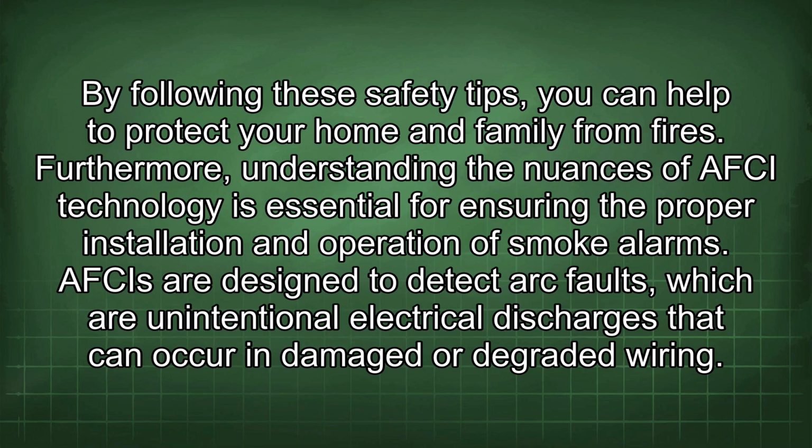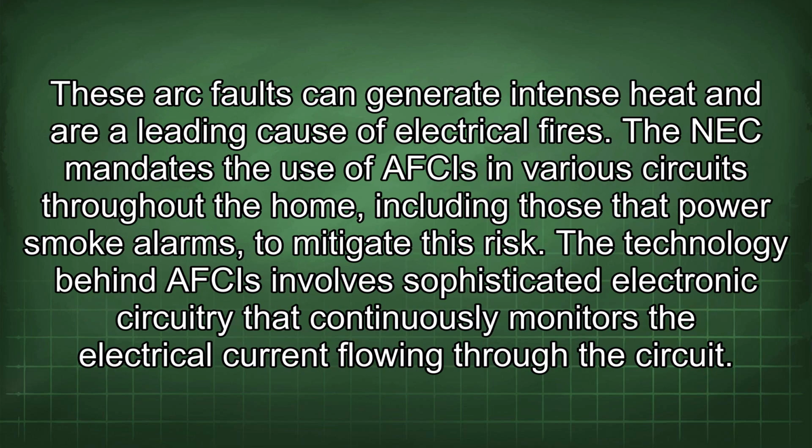Furthermore, understanding the nuances of AFCI technology is essential for ensuring the proper installation and operation of smoke alarms. AFCIs are designed to detect arc faults, which are unintentional electrical discharges that could occur in damaged or degraded wiring. These arc faults can generate intense heat and are a leading cause of electrical fires. The NEC mandates the use of AFCIs in various circuits throughout the home, including those that power smoke alarms, to mitigate this risk.